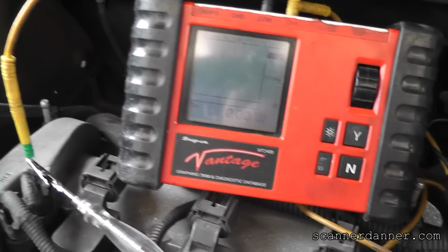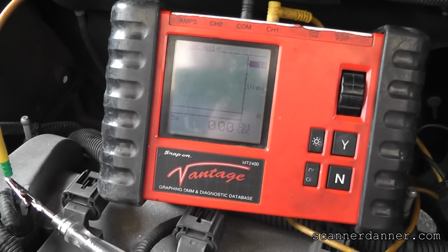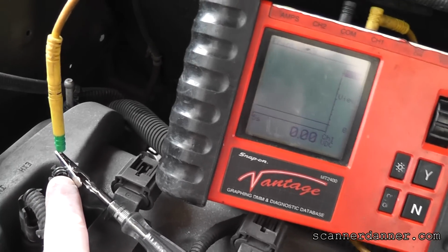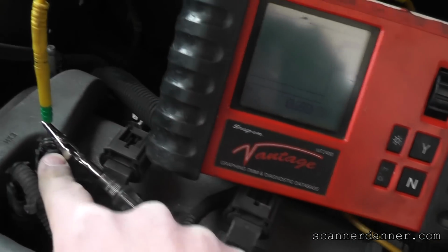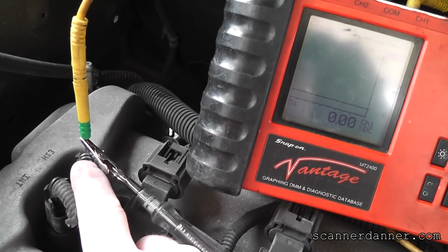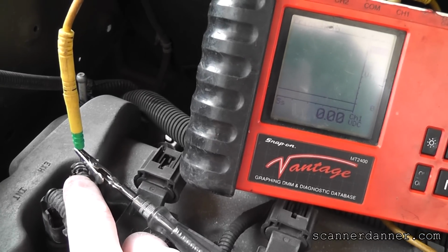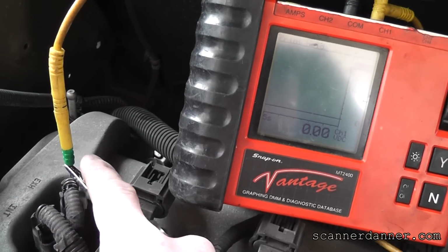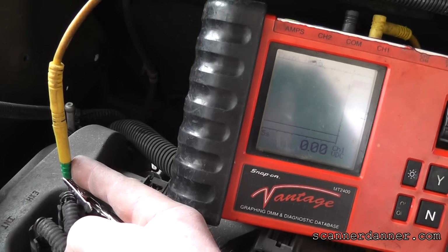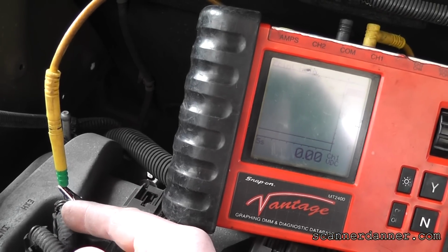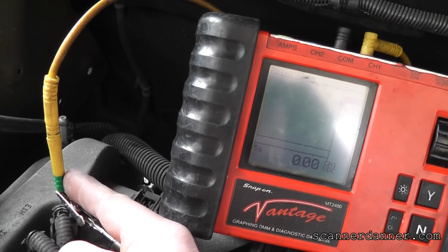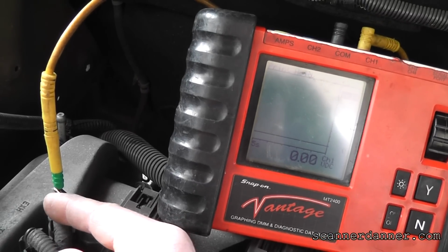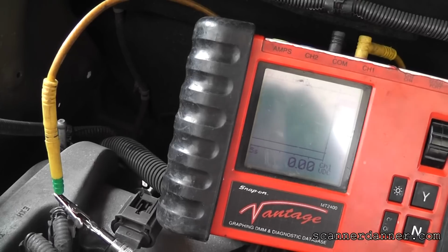So nothing wrong with the circuitry here, guys, at all. I could jump over and show you the ground wire too, but I'd have to cycle the key again. You know I should, because some of you guys are going to question it. I'm telling you I don't need to check that ground. If you guys are paying attention, here's why. I did already, but I don't need to check it again because when I started I had 0.93 of a volt on this wire. If I had a bad ground causing this solenoid to not work, I would have had that same 0.93 of a volt bias over here on this ground wire. I did not. So it told me the solenoid is open. It's exactly what we have.